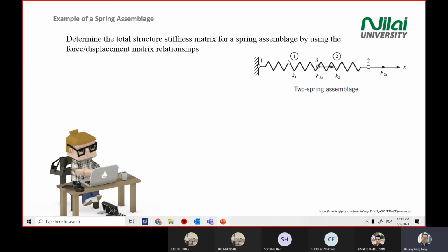The simplest one is 2 node. So for element 1, you have node 1 and node 3, position 1 or 0.1 and 0.3, that tell you what is happening to element 1. Element 2 consists of 2 points also, but the point numbers are 3 and 2. K is the stiffness matrix: K1 is for element 1, and K2 is for element 2.